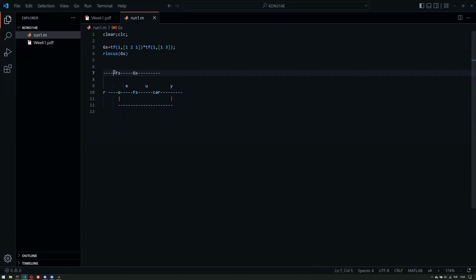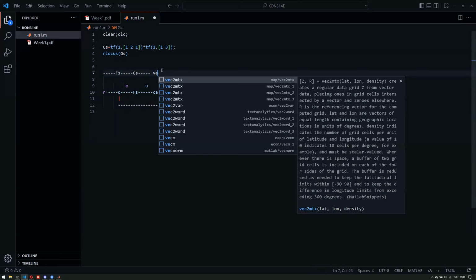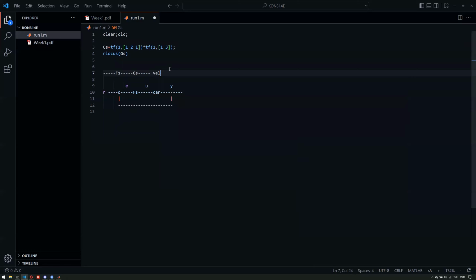Here, we don't really look at the velocity of the car. We don't really know what its velocity is, but based on the model itself, what I can do, for example, is give it 3 times the input that I actually want to give, apply it to the system, and hope that eventually I'll get to that speed.